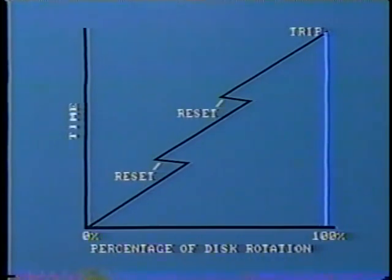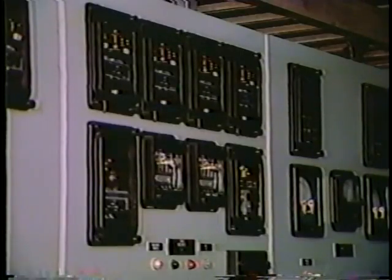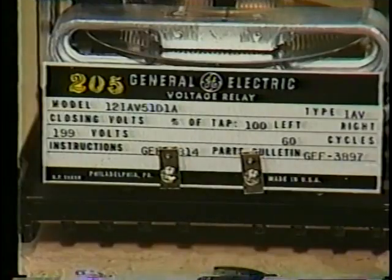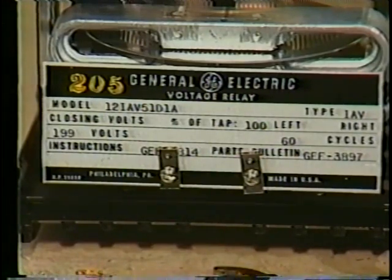If a repetitive fault occurs, the disk may not have time to reset completely, and each repetition may cause the disk to creep forward, and so after 2 or 3 repetitions, ultimately trip. These limitations must be borne in mind when calculating relay settings. Generally, overcurrent relays are constructed as single-phase units, and several relays are required to provide 3-phase and ground protection. The same type of relay with similar characteristics but different wiring is also used for over and under voltage protection.